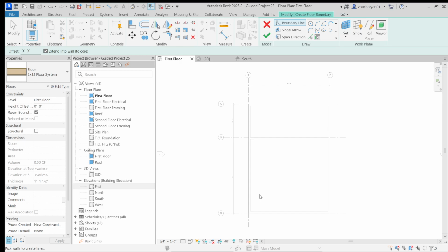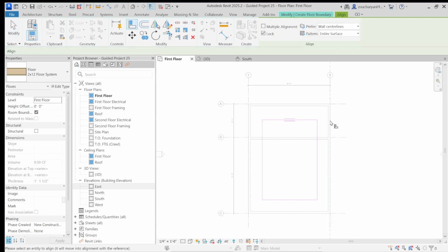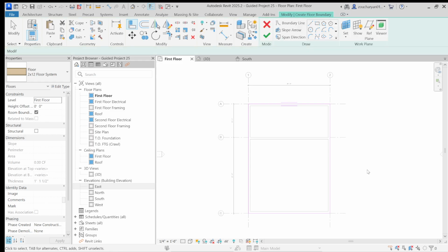Now this whole floor system is going to follow our outside grid. The whole house needs a floor. Do a rectangle, bang, bang, a line tool, and line that up to our grids. This is going to sit on top of the foundation wall. Notice these double lines here. Don't worry about those.